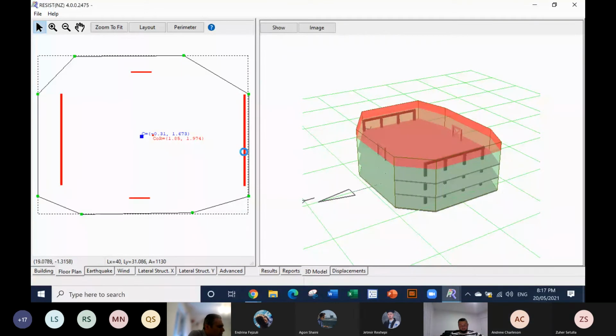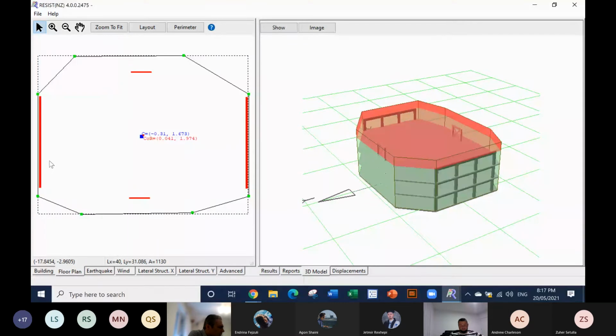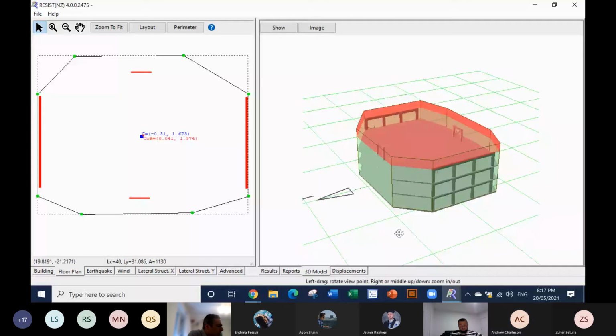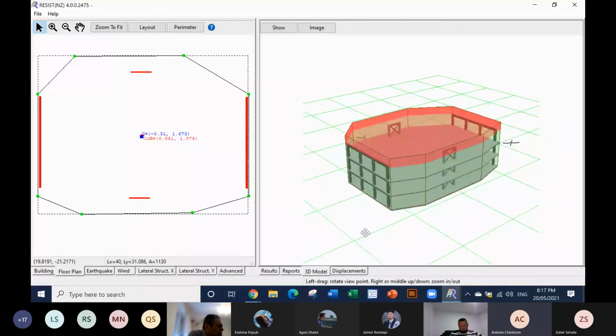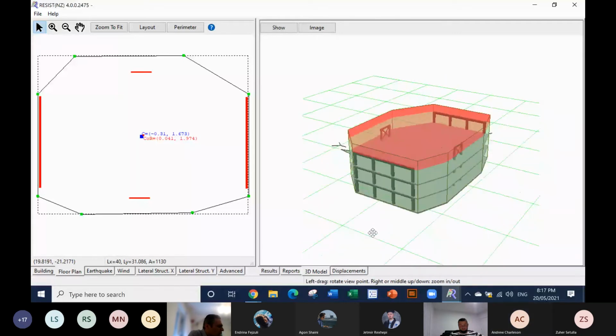I might add here also the parameter of the building height. So the moment frame system is effective for a certain amount of building height up to some certain point, and also by the length of the base between the columns, the spacing between the columns. And of course, when going higher and higher with buildings, then we are imposed to use additional lateral resisting mechanisms.